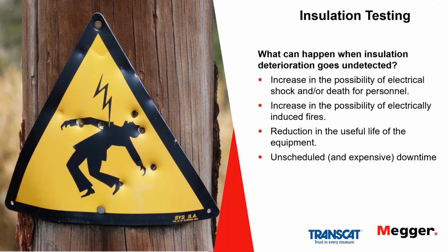In the environment in which it's operating, dirt and corrosives and oil and things like that may build up, and that promotes the flow of leakage current, and it's trapped in a relatively narrow space. It's not enough to trip your breakers, but heat is gradually accumulating, and you can get spontaneous combustion of things like oil and dirt, and that's where a lot of your industrial fires begin.